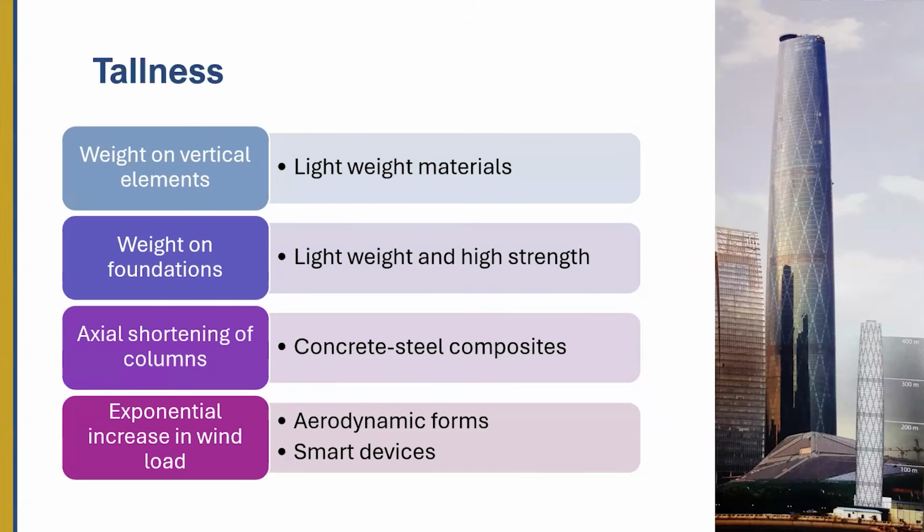Because of that, after some point, the wind load management becomes difficult, and it's not surprising that many buildings at the top are like this, like the Eiffel Tower. The Eiffel Tower was perfectly positioned to manage that wind profile. I showed you last time, the shape of the Eiffel Tower was derived from the wind profile variation, even in 1890. So that's why Burj Khalifa is like this, and many buildings are like this. They try to keep the wind force constant. Many times that will not be enough, so we will need to add smart devices to handle that, like dampers, different kinds of dampers.